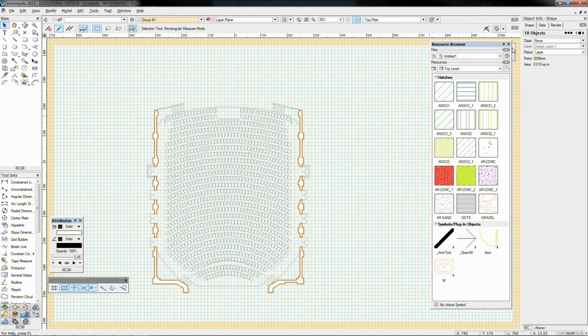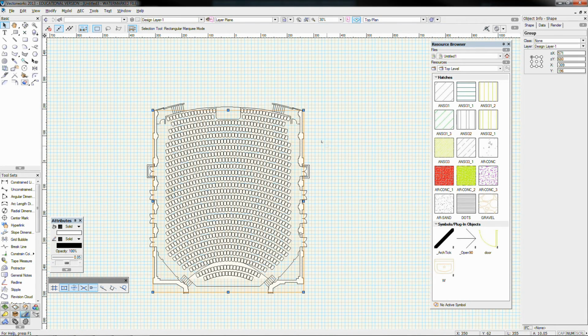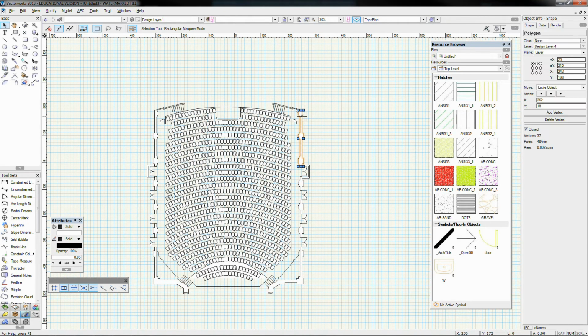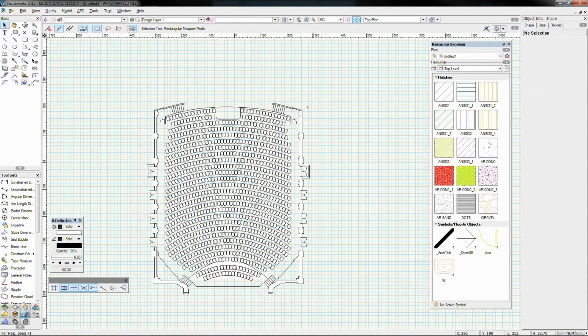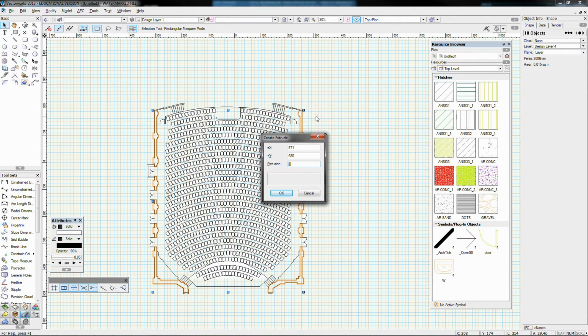What I am going to do though, I'm going to ungroup these objects here. I've got 10 objects. Now what are they? Are they polygons? Yes they are. So I'm just going to grab those together, ungroup again, so I've got all of those selected, and immediately I'm going to extrude those objects, presuming that they're all polygons, which they seem to be. I'm going to have to guess here because I couldn't find the actual heights, but I'm just going to say, oh, I don't know, 8 meters. Let's try that out for starters.